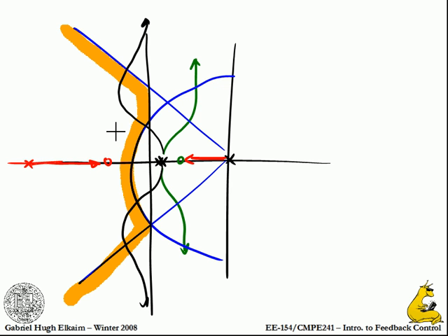I know I can't reach my specs just by doing my root locus. I figured out I couldn't reach it naturally, but I understand how adding different things is going to change my root locus. And therefore I say, okay, I need active compensation. I need compensation that is more than just proportional feedback. I'm going to need feedback plus, in this case, a lead network. I'm going to put this in, and it's going to bend my branches, not much, by the way, but enough to get into my area of acceptable specifications. And I say, aha, now pick those 2 points and I'm done.